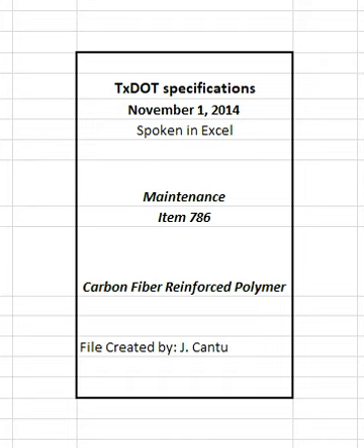3.2 Working drawings. Working drawings are not required for CFRP application to confine or protect concrete members, unless otherwise shown on the plans. Provide working drawings and calculations signed and sealed by a licensed professional engineer for concrete member strengthening. Include in working drawings repair locations, relevant dimensions of the system, details of the number, thickness, and orientation of carbon fiber layers, locations of splices and corresponding lap lengths, number, size, and location of CFRP anchors, and construction procedures specifying the individual steps in the installation process.